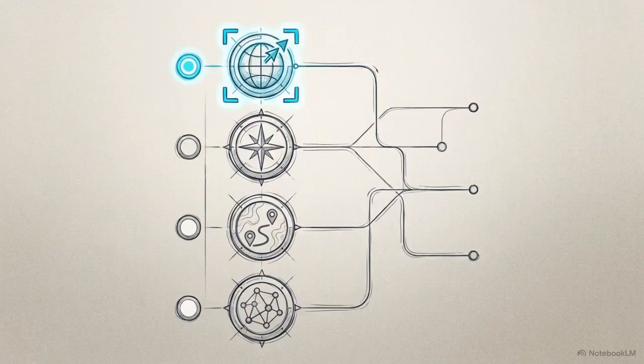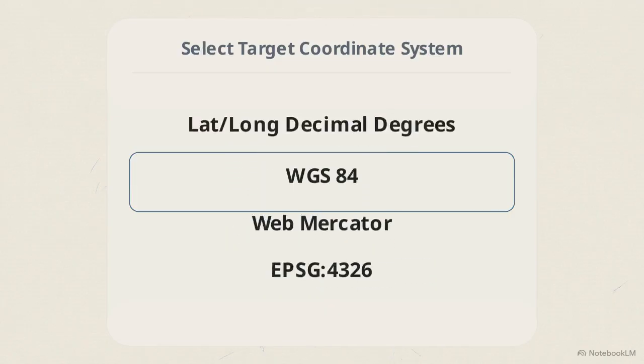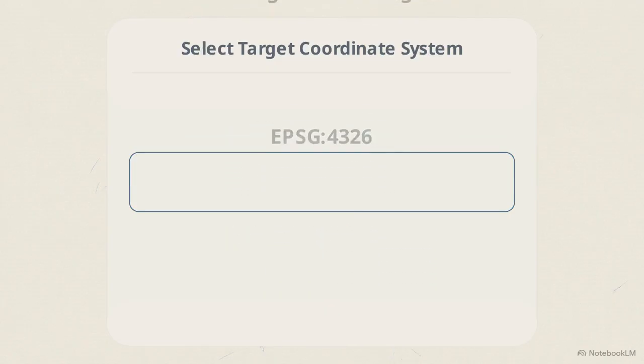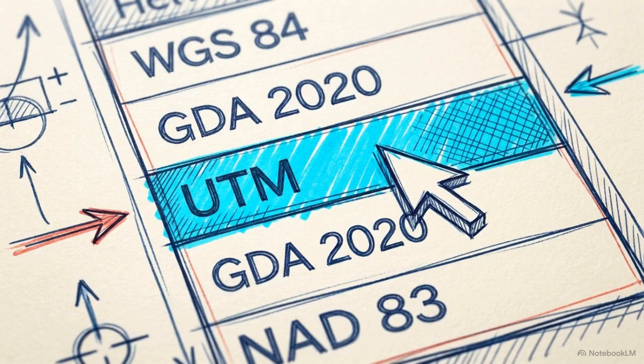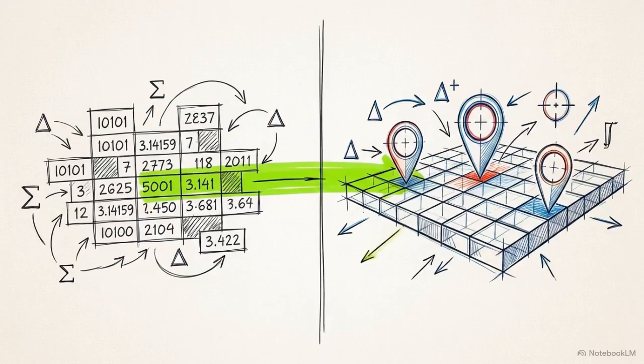With the file prepped, move to section 2 of the interface, the Convert to targeting area. This interface represents the various mapping systems available for output. The tool supports formats ranging from military grid reference systems and township and range setups to what3words. For our demonstration, we will finalize our selection by locking on to UTM as our target format. Defining the target format ensures the output matches the exact coordinate system required for your project.